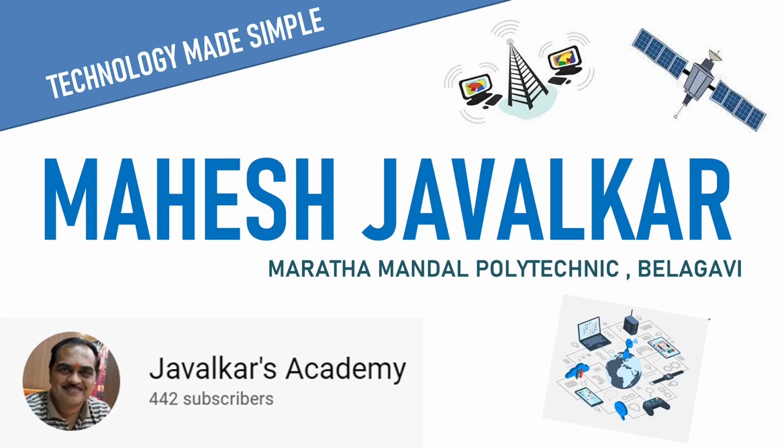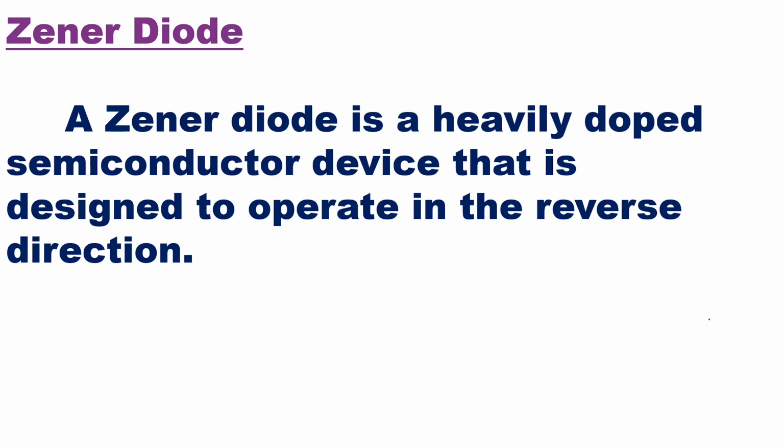Here, the important things to understand first are the structure of the Zener diode and how it is different from the conventional diode. Then we'll see the symbol, and then we will draw a circuit where we use the Zener diode as a voltage regulator, and see how the voltage is regulated. As far as the basic definition is concerned, a Zener diode is a heavily doped semiconductor device that is designed to operate in the reverse direction.